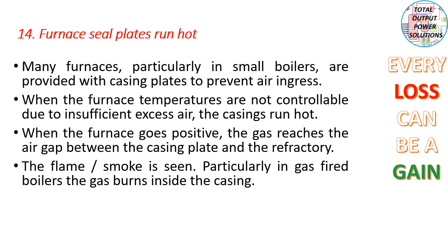Furnace seal plates running hot. Many furnaces, particularly small boilers, are provided with casing plates to prevent air ingress. When the furnace temperatures are not controllable due to insufficient excess air, the casings run hot. When the furnace goes positive, the gas reaches the air gap between the casing plate and the refractory. The flame and or the smoke is seen, particularly in gas-fired boilers. The gas burns inside the casings.